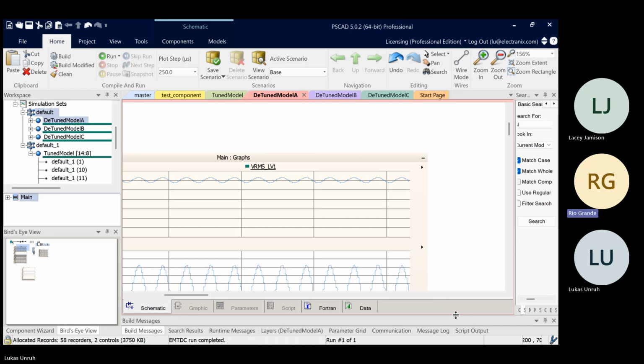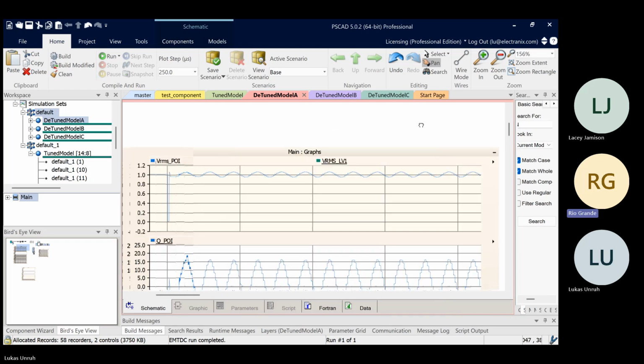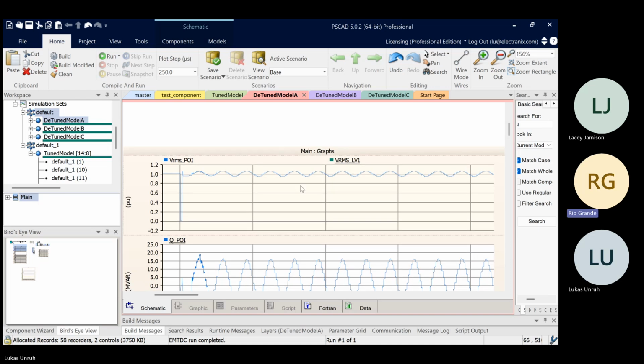The example we saw yesterday had just two contingencies that caused that low SCR. The other time it was 10x stronger. So that's something to keep in mind when you're trying to determine if it's weak or not. It's both: is it weak in the system intact in the serial mission planning world, or is it weak in the N-1-1?